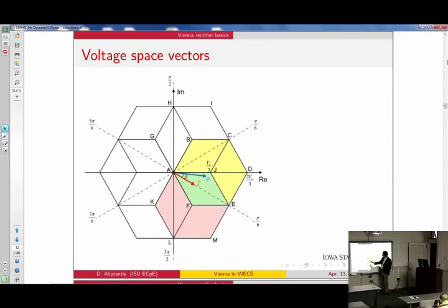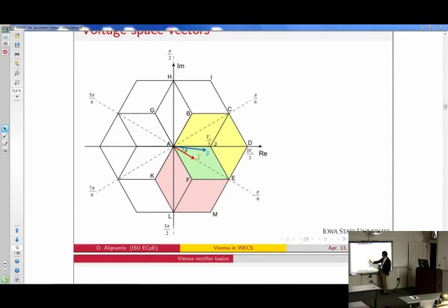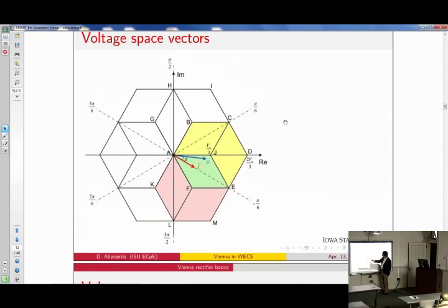So the key is, look at what the current is doing when it is at exactly minus 30 degrees, for example. At that moment, the current is switching from one hexagon to the next. Okay? What happens is that at that point, if you want your transition to be smooth for the voltage, you can only generate a voltage vector that is inside the intersection of these 2 hexagons, which is this green parallelogram. Just believe me, that's true.